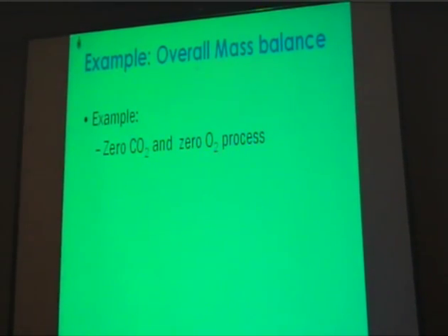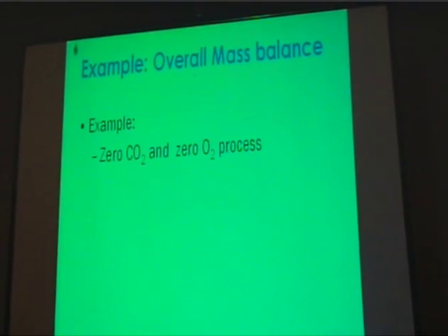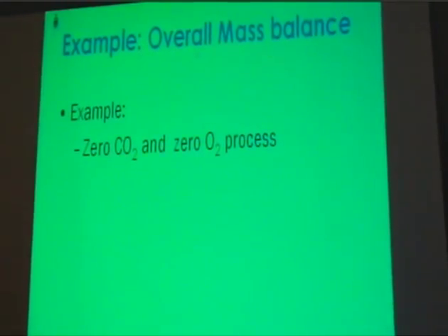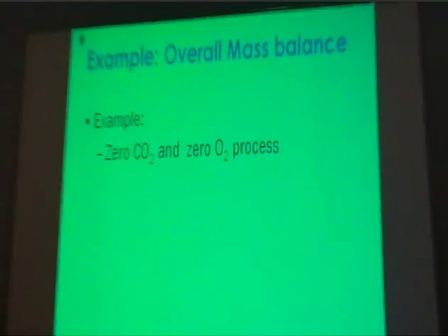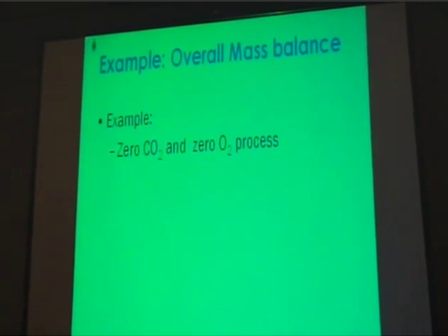Not making use of oxygen in our process has a massive capital effect on our plants, because reducing the oxygen consumption of our plants could mean possibly the elimination of an air separation unit, which, working in this field, you will know is a massive energy consumer and adds inherently to the CO2 emissions for our process in generating the electricity or power to run that.